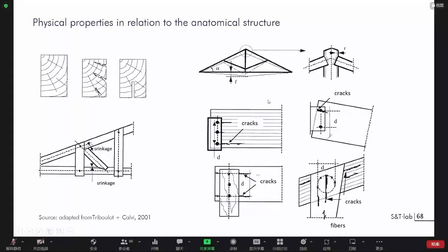Even with a connection, if we have a steel plate, or two different directions of timber, the one being vertical and the other, let's say, horizontal or almost, or with the connection with steel plates that won't change dimension with the temperature, it will drive the timber to change its own direction and you will have cracks appearing in the joint of timber.